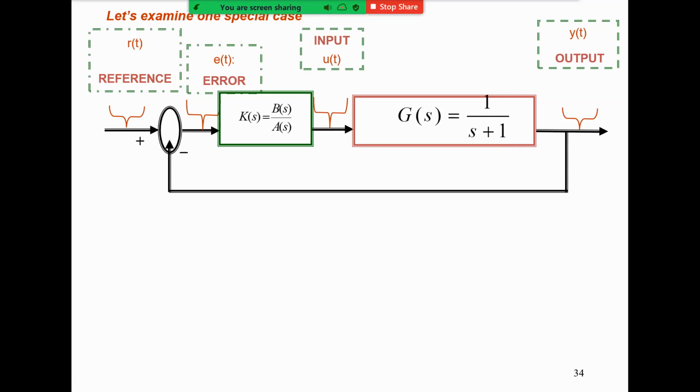Of course, you know that there should be an integrator. But now let's assume that you don't know that. You already forgot that. You don't have that knowledge about implementing those magic integrators. So let's start from scratch and find out what is the requirement on this controller to make this error signal go to 0.